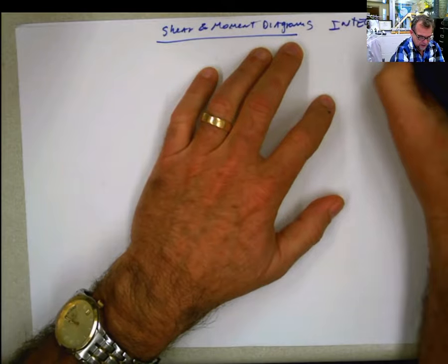That point is A, that point is B, and this point here is called C. First things first, same thing: a line at the beginning, a line at the end, and wherever you have a change, which in this case we demonstrated was only at this point. Wherever the load begins, wherever the load ends, no concentrated load, no concentrated moment, nothing else. That's it. A horizontal line for the shear, in kilonewton, and a horizontal line for the moment, in kilonewton meter. This baseline represents 0, and everything I plot above is positive, and everything below is negative.